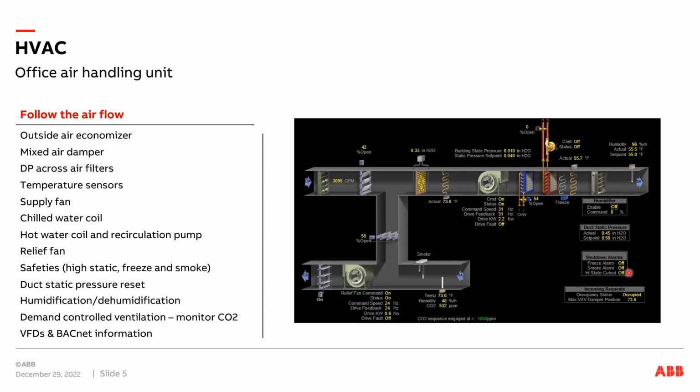So you can see status here. These safeties all get wired back into the VFD that's running this air handler. And then this whole system is connected via what's called BACnet. That communication protocol brings all this data back up to the computer so I can see exactly what's going on. There's been times where we had a nuisance fault once on a high static safety cutout, and this particular air handler's up on the roof.